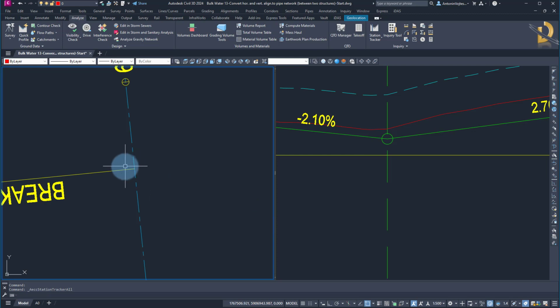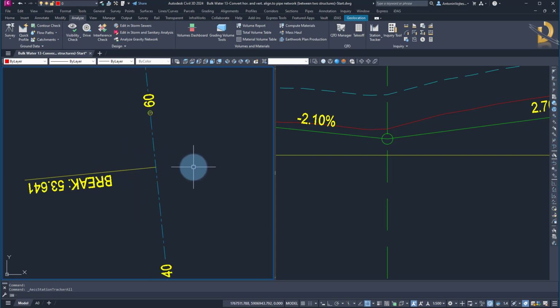So if I add a circle here with a radius of 4 meters, then it will actually be 1 meter left, 1 meter right. Because in a scale 1 in 1000, if I use a circle with a 2 millimeters diameter, it will be 1 meter left, 1 meter right. And for a scale 1 in 500, I need to multiply it by 2. So I need a circle 4 meters large.